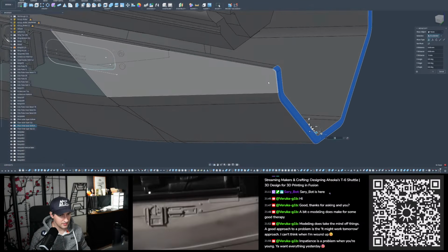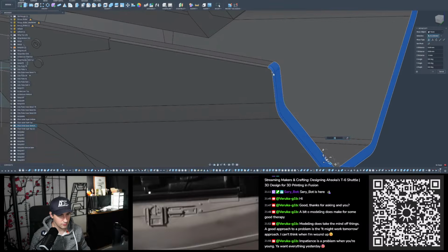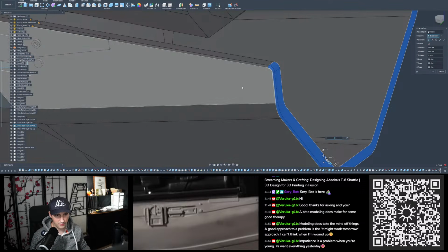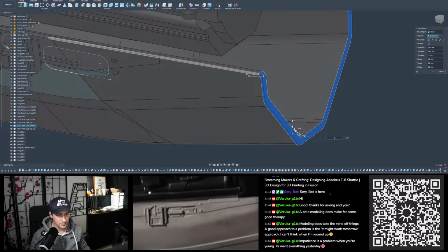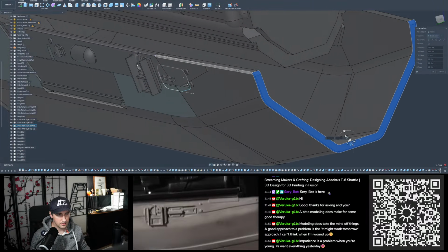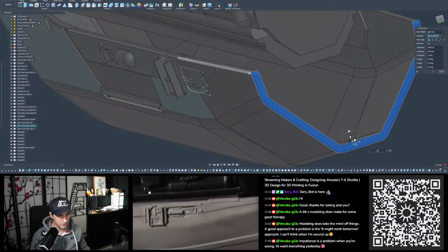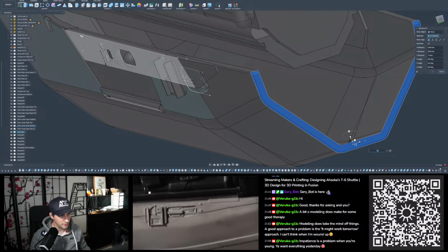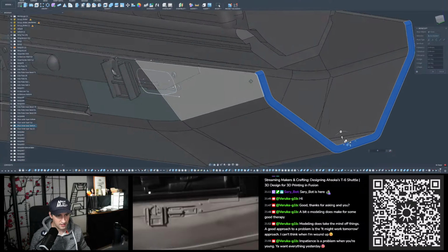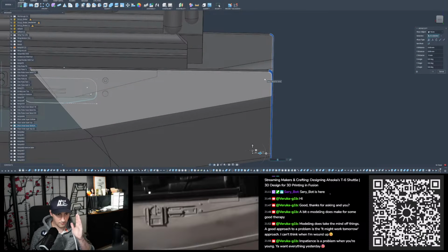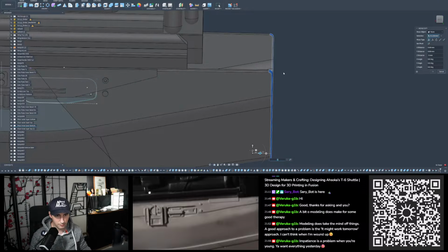The next easiest thing would be to remove the fillets here, the small ones, and then move it, and then just add them again. But I don't think it will let me remove them because I then have to remove those as well, all the way to the front. And so I think it's better to just cut it and be done with it.